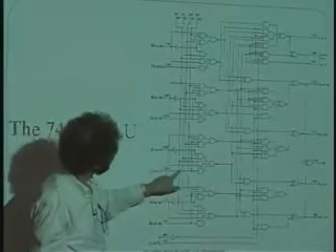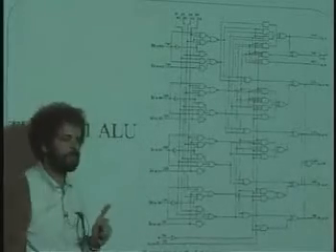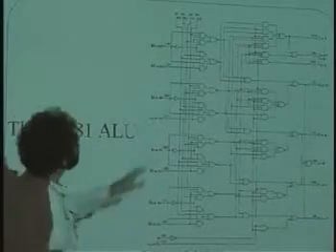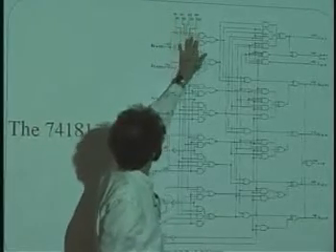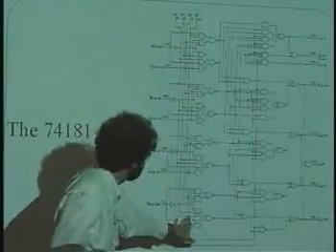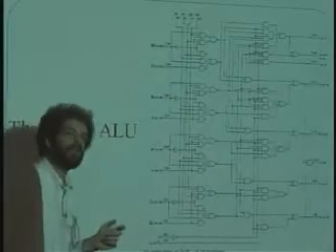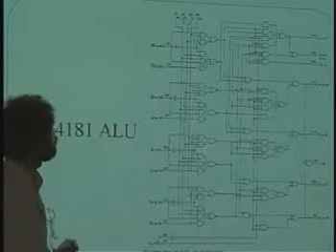Okay? And if you go through the logic here, what fools you a little bit is that this ALU doesn't only add. In fact, this ALU has 4 bits, S0, S1, S2, and S3, that go down all the way down here, and that plug into all these gates, and they allow it to do add, subtract, and or all kinds of fun things.